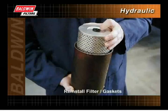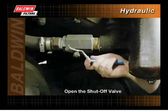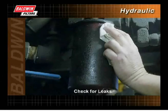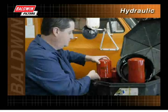Reinstall the filter and all necessary gaskets. Replace the housing cover retainer nut. Open the shutoff valve. Make sure the fluid level is full, and finally, start the engine and check for leaks. Remember, when disposing of used hydraulic filters, follow all environmental regulations in your area.